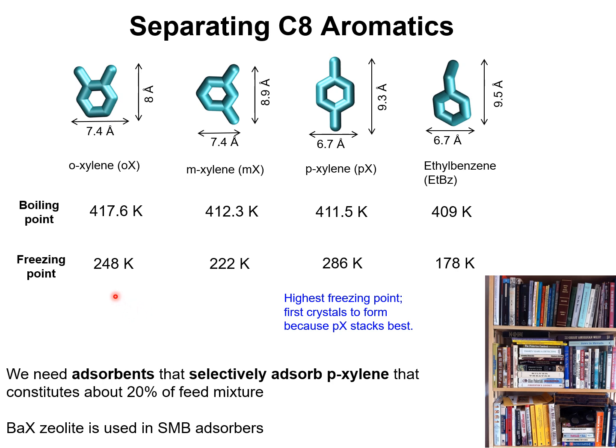However, there is a significant difference in the freezing points of the C8 aromatics. The component with the highest freezing point is para-xylene, and when the solution of C8 aromatics is cooled, the first crystals to come out of solution consist of para-xylene.